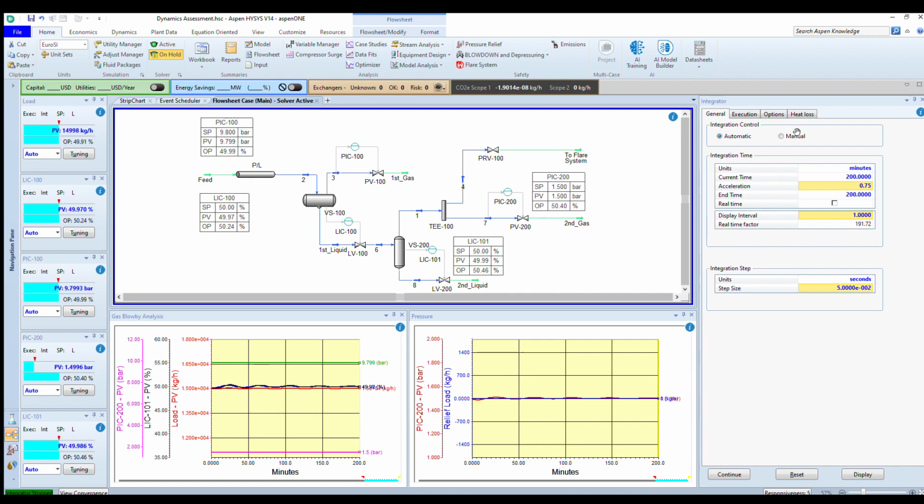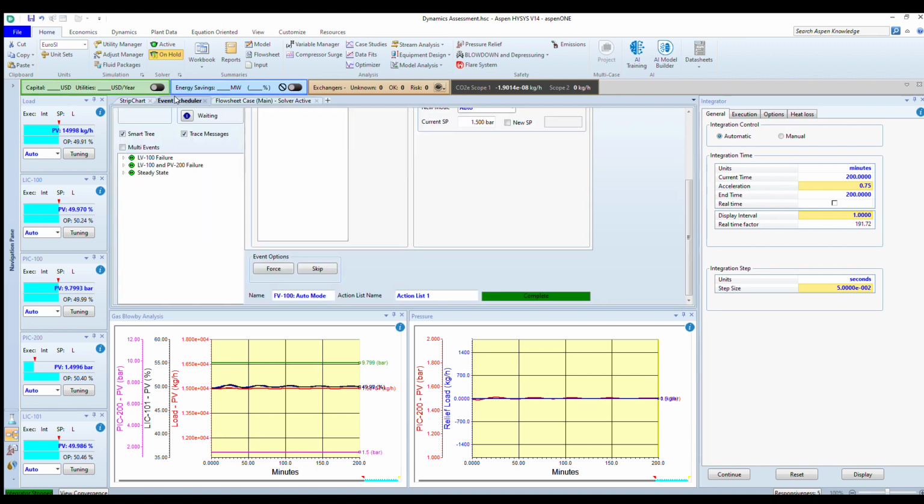system. And from that perspective, we have improved and enhanced the steady state a little bit, including the basic process control system, to see the knock-on effect and the consequences, whether positive or negative, on system dynamic response during relief load. In dynamic, we have created an event scheduler considering all potential scenarios.